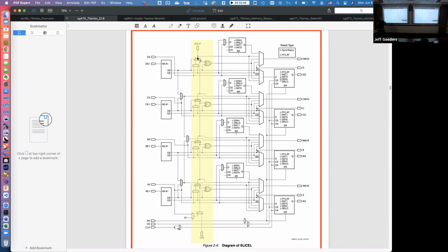So one of the things Vivado has to do as it's synthesizing and placing and routing your circuit is, if you have various flip-flops and they are cleared on different conditions, it's going to have to figure out how to group the ones that use the same clear logic into a slice because they all have to share the set reset. Go ahead. Can they be different polarities?